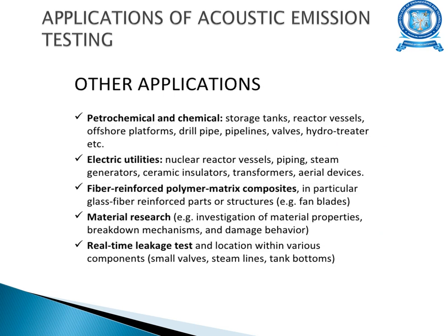Other applications involve acoustic emission techniques. It's used in petrochemical and chemical industries for storage tanks, reactor vessels, offshore platforms, drill pipes, pipeline walls, hydrotreaters, etc. And electric utilities like nuclear reactor vessels, piping, steam generators, ceramic insulators, transformers, and aerial devices are tested using acoustic emission.